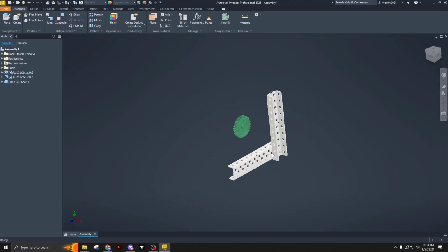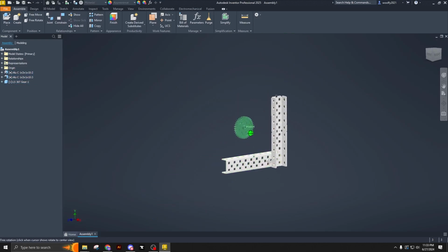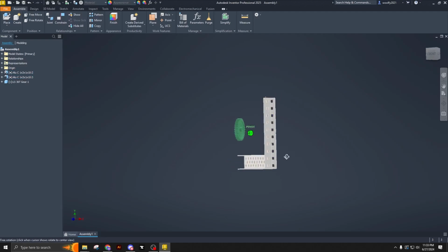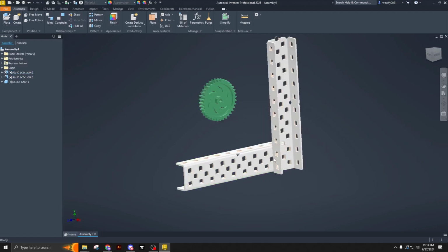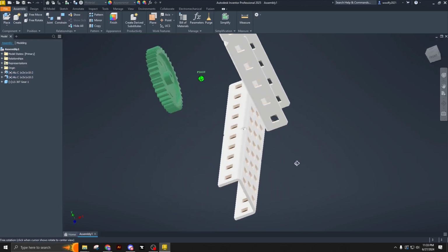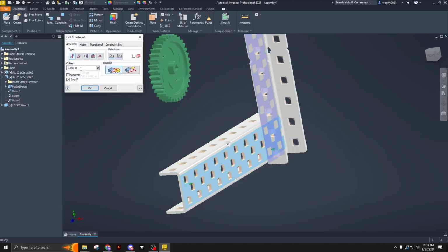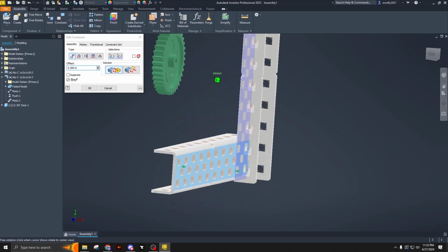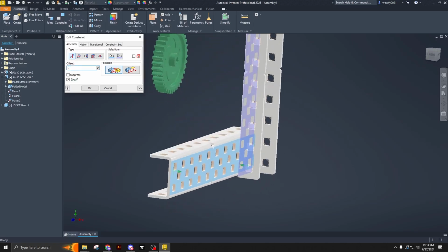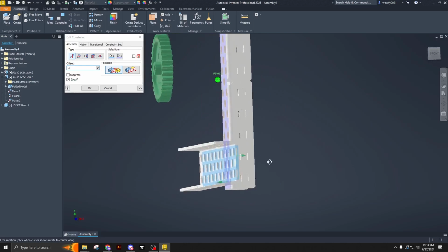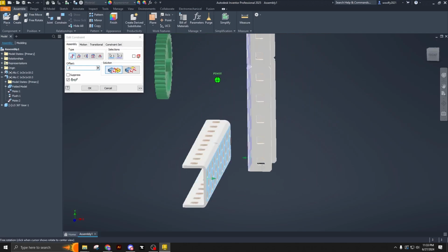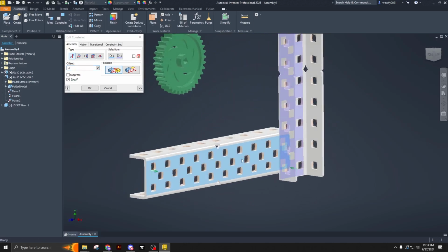Another thing you can do is, let's say I need room to put a custom part from here to here. I don't want to bend it, I want it to be all straight here. I can select this, and if I double click on it, I can add in an offset. If I make this 0.5, it's going to offset it 1/2 inch. That's probably a little bit too much, but you can use offsets to help move stuff around and determine exactly how much spacing you need.